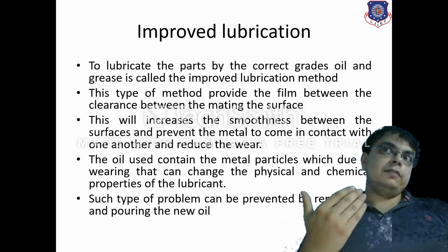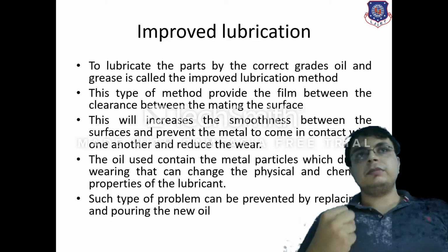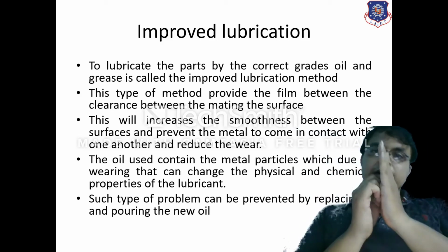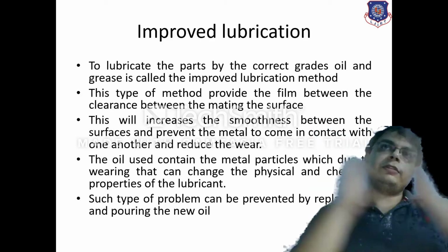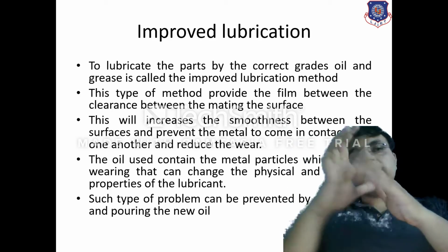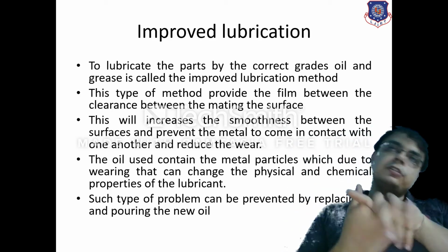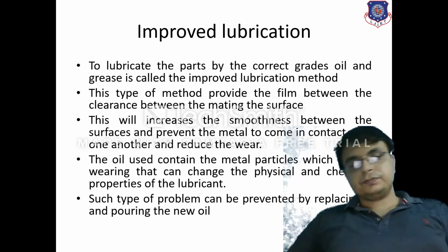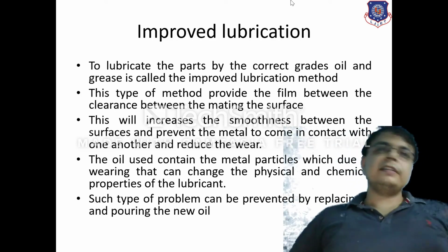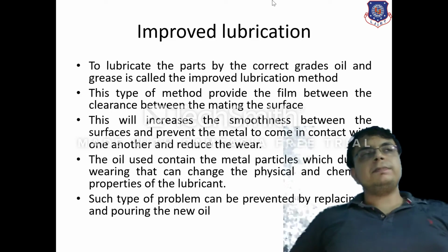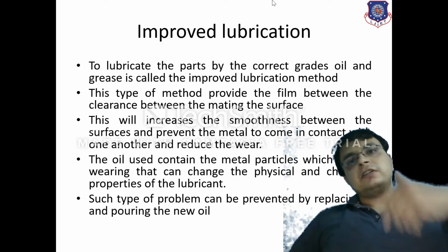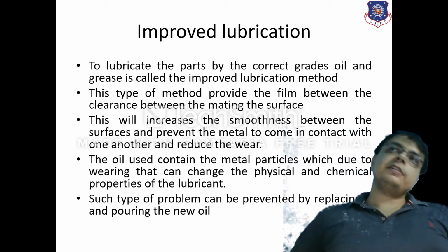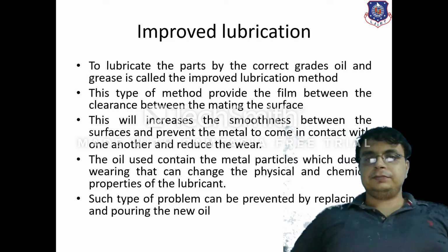Such an oil film is also harmful to the machine because it will again cause collision, because between the two surfaces there are small particles which are in contact with both surfaces. When the particle is between both surfaces, it will cause abrasion to the surface. The surface will get rough and the wear will be more. So the only thing required is to replace the old oil with new oil, and as a result the particles present in the oil will get replaced.